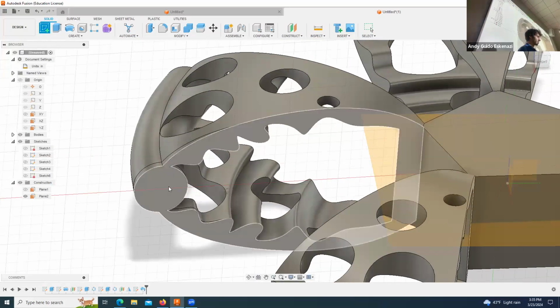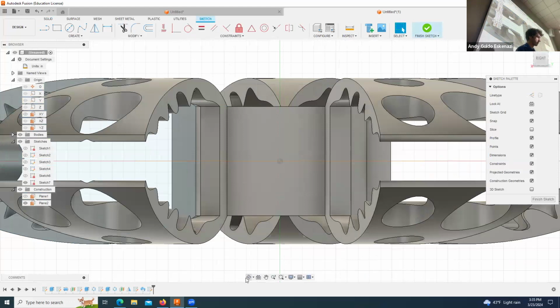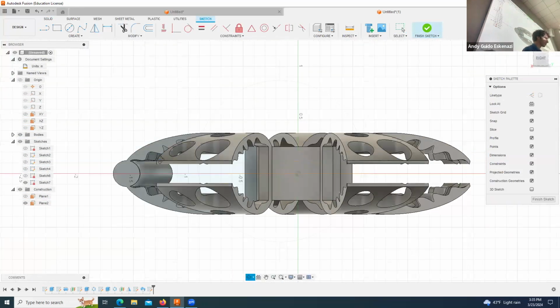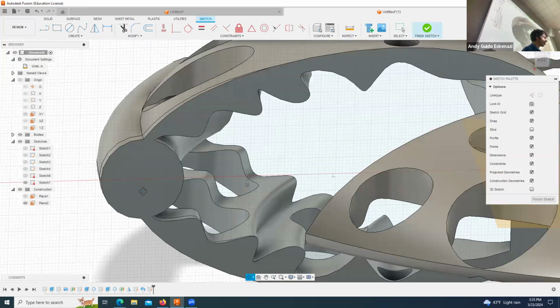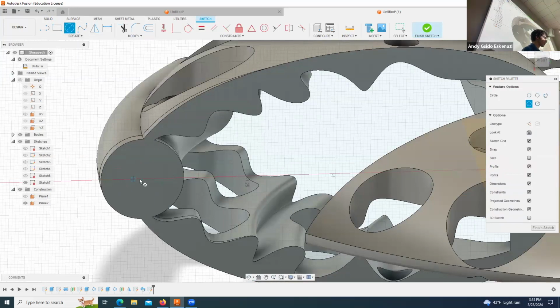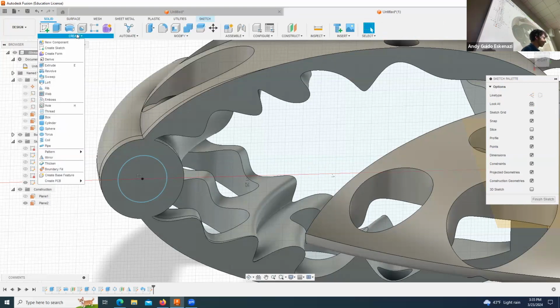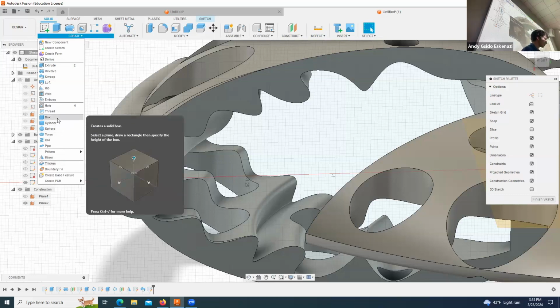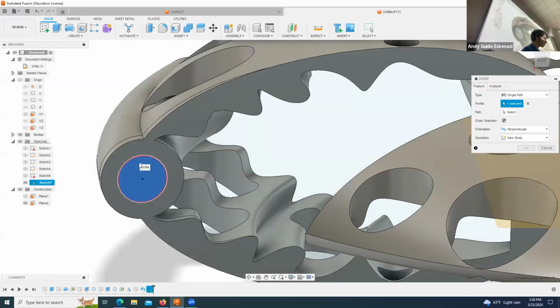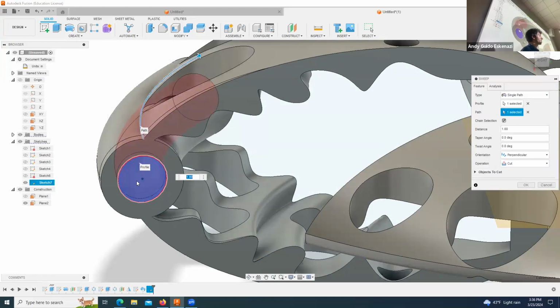So now once you've done that, we can do something even better, which is now you can go here to create sketch, also on that very same face. What I can do is draw, say, another circle there, something along those lines. Then I can go to solid, then to sweep. There we go. And I can say, yes, I want the exact same path, but this time I want to cut. Does that make sense?